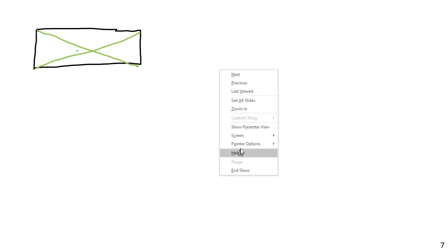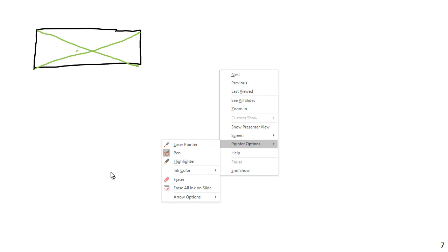Again, we said that load will tend to go to the closest location. If we assume triangular loading, this piece of slab right here, this piece of live load and dead load, is it really going to go all the way over here? Is that the closest beam at that point? No, the closest beam would be here or here. Loading will tend to go to the closest location. So instead, what we tend to do for things that are rectangular is more of a trapezoidal loading.